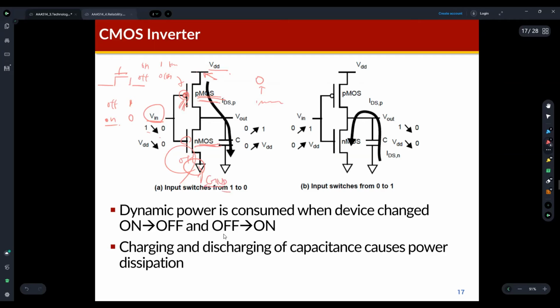The node shared by the PMOS transistor and the NMOS transistor is the output of this inverter circuit. As I explained, every circuit has a parasitic capacitor. The voltage level of this circuit is determined by the amount of charge filled in this parasitic capacitor.